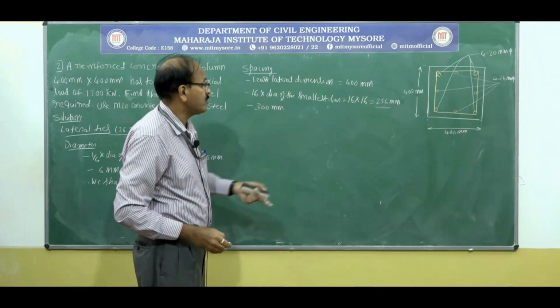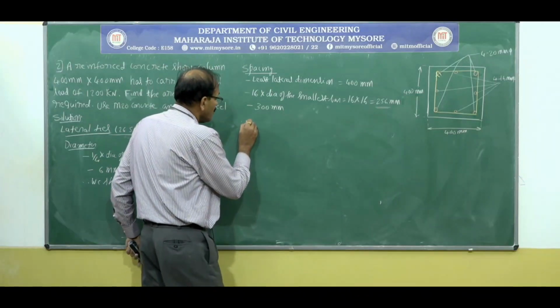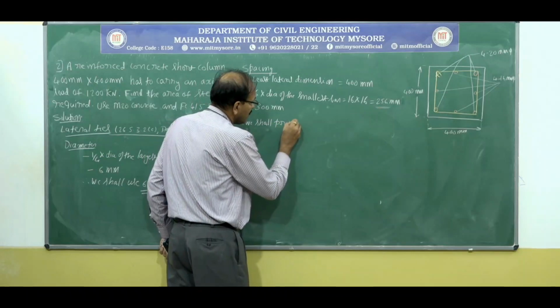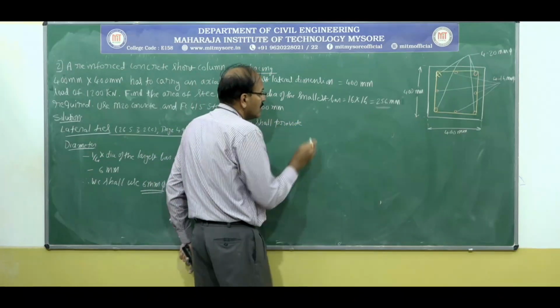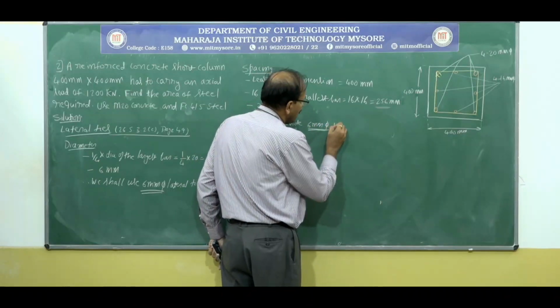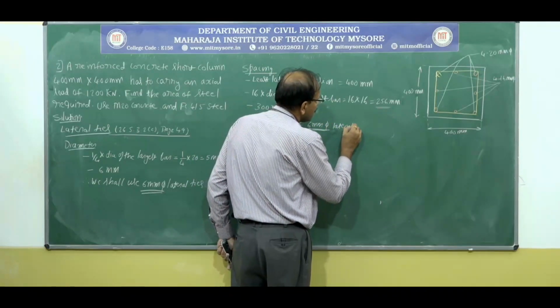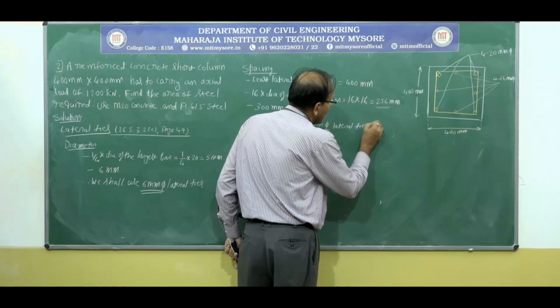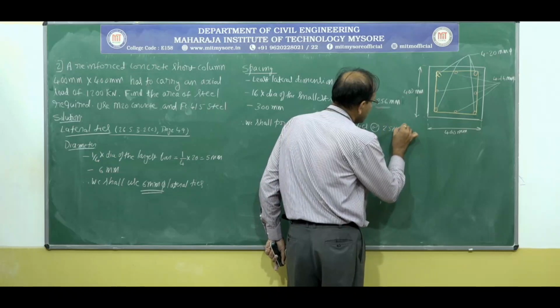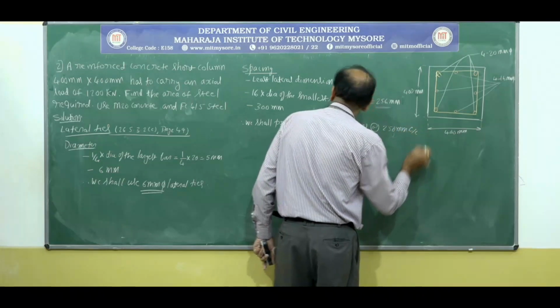Therefore, we shall provide 6 millimeter dia lateral ties at 250 millimeter center to center.